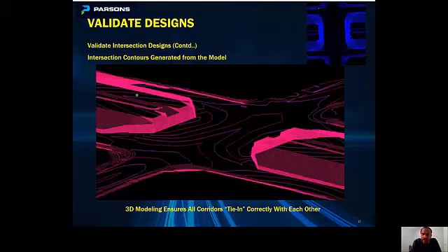We were able to catch this during the QC process, and later resolve that issue. In the pink contours, you can see everything worked out pretty well, and the break lines were triangulated correctly, and the bottom of wall and the finish grades were generated correctly in 3D.